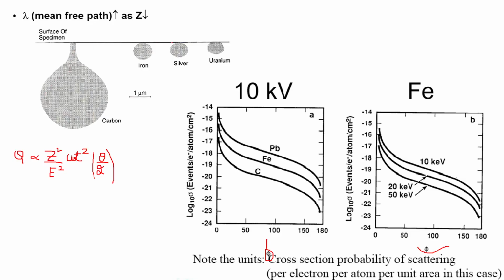In the higher atomic number case, it will initially have repulsion from the electrons present in the specimen, so it will not have this neck shape, because it is repelling from the initial phase only. As a result, it has a small interaction volume and follows a sphere kind of shape as compared to the pear shape.